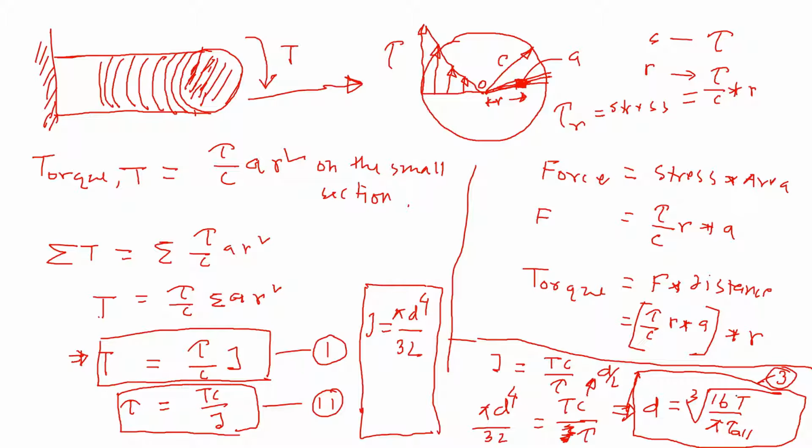When you want to find the diameter of a shaft, we have to be within the limit of that material, the allowable shear stress, instead of just the shear stress as in the general formula in the other 2 cases. But this one is a design. When you are asked to design a shaft, you use this formula, and if you don't use the allowable shear stress, the material will eventually break, so the diameter will not be accurate.